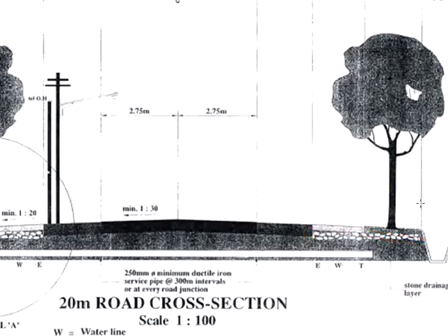Under some circumstances, the designer may choose to have the footpath slightly higher than the pavement, and the edge of the footpath here will be considered as the curb. This is another option. Now, if you choose to design in this manner, you will still need to provide openings for the water to flow into the drain.